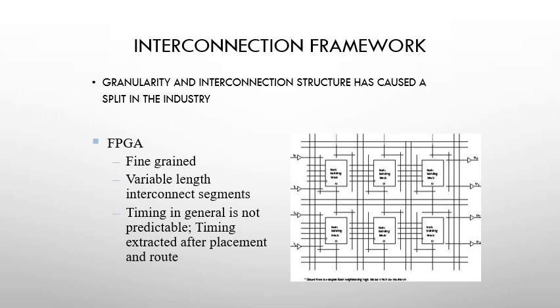Then the interconnection framework. Each and every block is connected with connecting wires, segregated with the blocks also. FPGA has fine grained, variable length interconnect segments. Timing in general is not predictable. Timing is extracted after placement and routing.